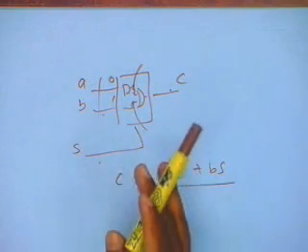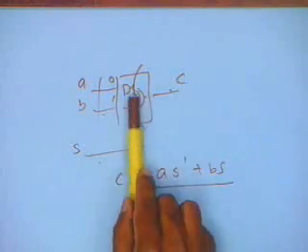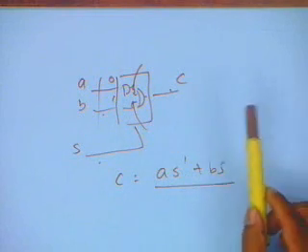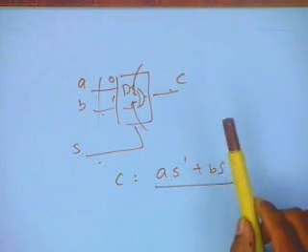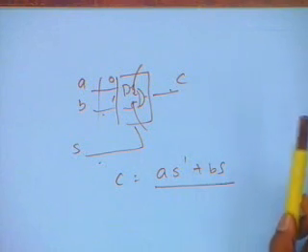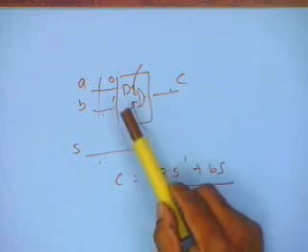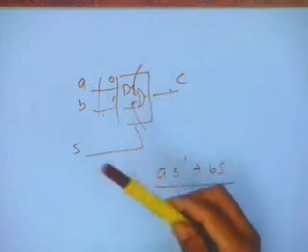But in some cases, if we make an assumption that faults at some of these nodes will reflect as faults at some other nodes, which will typically happen very often, and some test vector is there to include that fault, then these faults will also be detected. Of course, not explicitly, but it may happen because of the nature of the test vectors and the nature of the faults that they may reflect in some other.